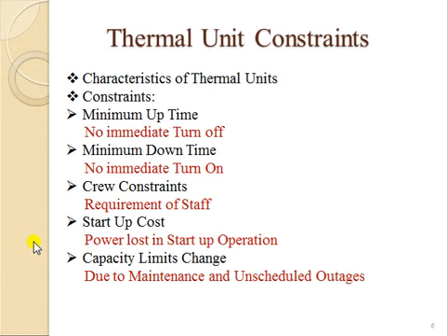Apart from this, as we have already discussed, a thermal power plant has some time lag before it actually starts supplying power. So whatever power is wasted from zero until it achieves the condition where it starts supplying power, whatever power loss there is in terms of megawatt, which is not useful for the grid, this operation is called a startup operation. So the cost related to this is called a startup cost, which is also considered in unit commitment. So this is also one constraint.